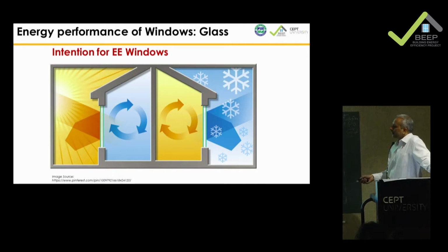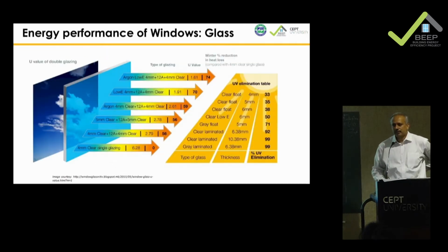So, that's the comparison: single pane clear glass, 0.9 U value; double pane, 0.48; and if it is insulated low E, you can really go down to 0.31. And then you start filling it with certain kinds of heavy gases, argon or krypton, and you start getting lower and lower U values. This is all engineering, not really meant for all contexts.